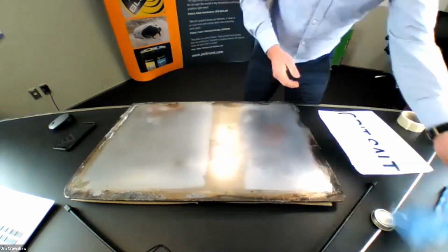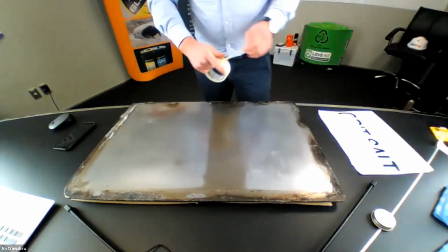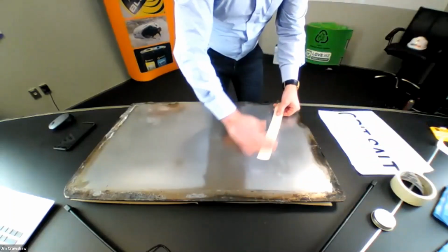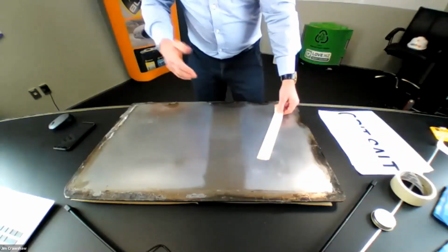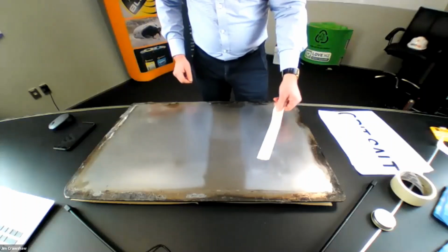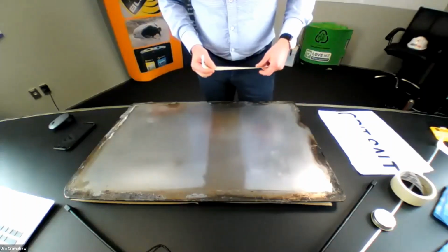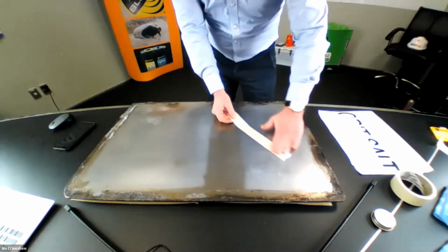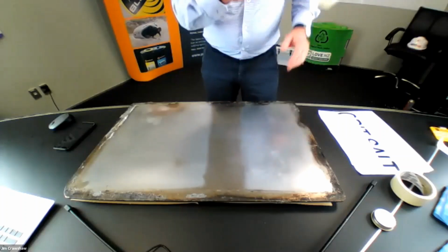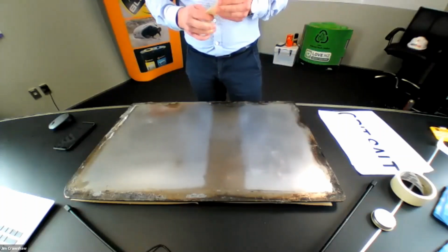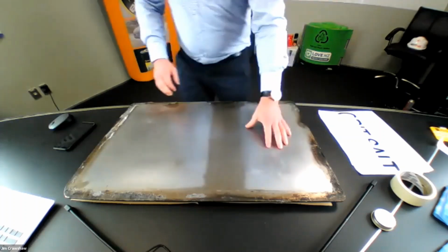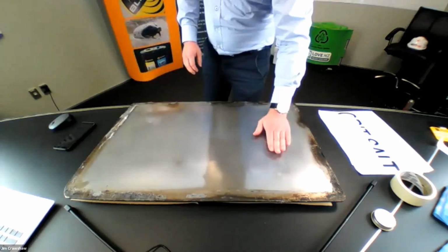So I'm going to give that a quick tape test. And if I'm still not getting good results, I'll be redoing this. So sticking it down, and just listen carefully. I'll try and be really quiet. So that's the kind of noise I want you to hear. I hope that came across okay. We're sticking it onto the mold nice and firmly, rubbing it, and you can hear that distinct sucking noise when you're pulling it off. That's what you want to be listening for, and that's how you want to be preparing the mold.